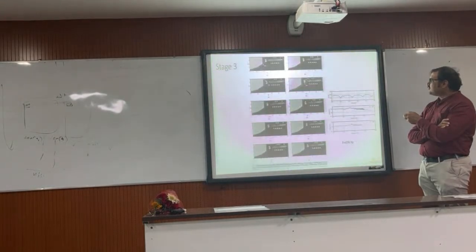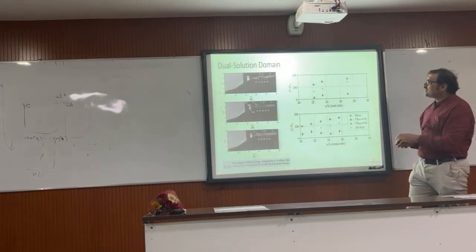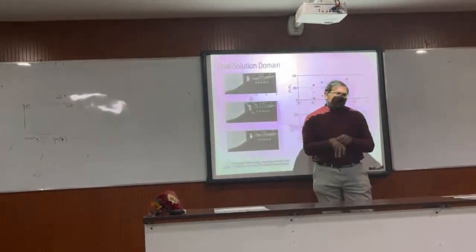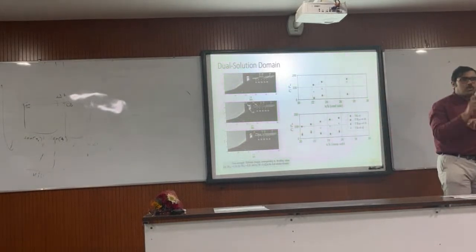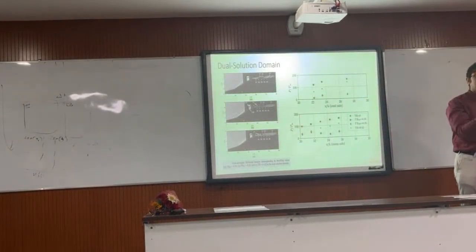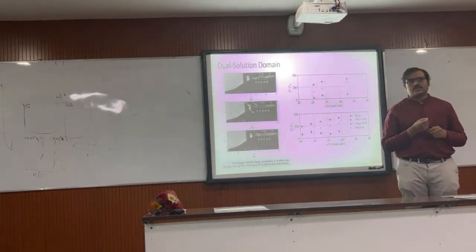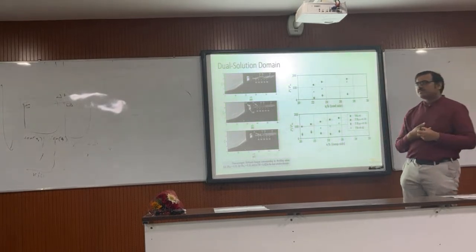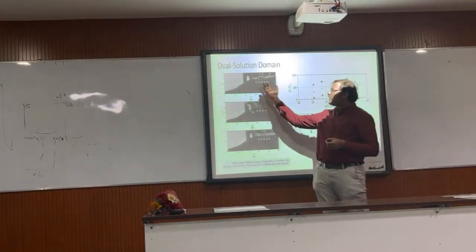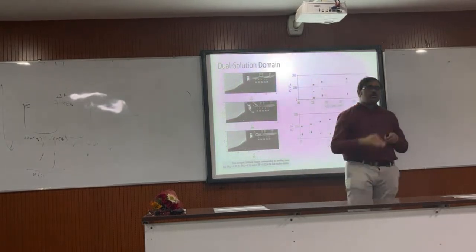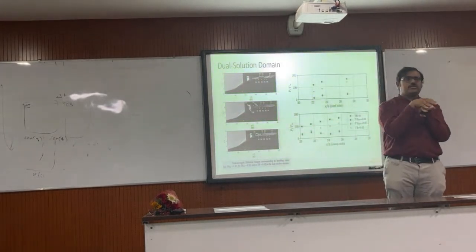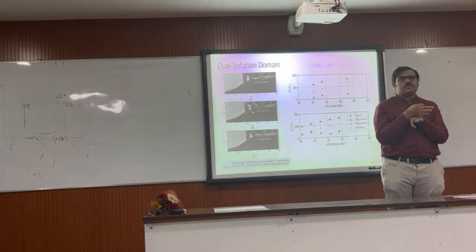If you have a pressure port, a tube, and mount the pressure transducer at some different location, then you have to account for that, and you have to ensure the holes are extremely small. But here, we have taken dynamic pressure transducers and mounted them directly onto the wall, flush mounted. So there is no gap; it is as if the wall is there.